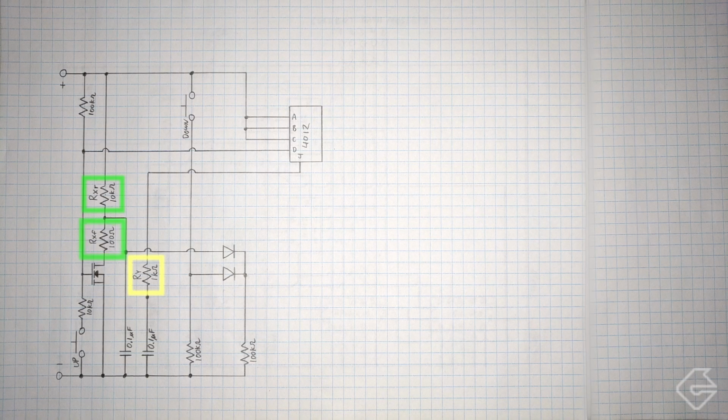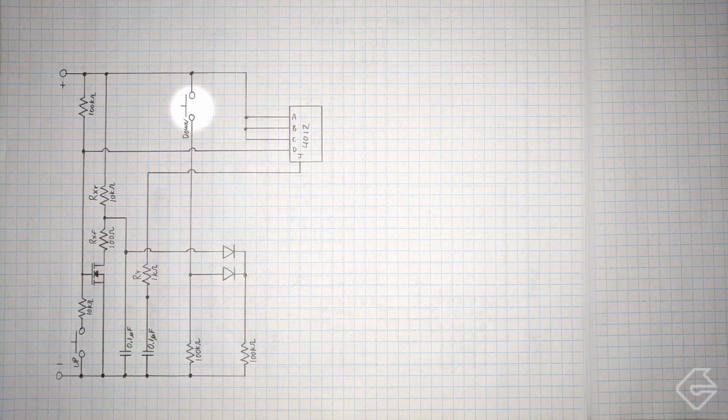I told you that was a little hairy, so I'm glad you're still with me, but we had to go through all that work to figure out what those values were. It was a little painful, but we're nearly done. So I've put the values in: 100, 10 kilo ohm, and there's our 1 kilo ohm. We also put in the 0.1 microfarad capacitors over here, and we still have the remaining circuit as we did before. I did add a little bit more here because I wanted to move a little bit further, so that we can talk about another challenge that I discovered. I put in the down button here too, just for completeness.